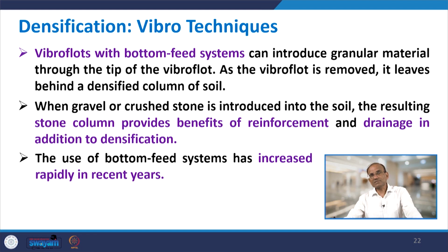When gravel or crushed stone is introduced into the soil, the resulting stone column provides the benefits of reinforcement and drainage in addition to densification. So, what happens? On one side you are densifying, and in case you are putting some gravel or crushed stones, introducing some material also, it will be a kind of stone column, which we will discuss in detail in the next part when we talk about reinforcement techniques.